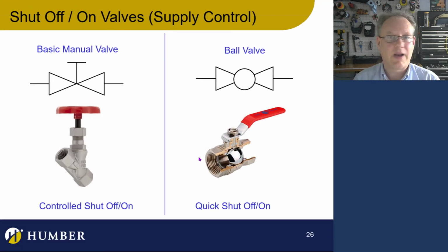So a little bit more ancillary equipment, some symbols, and then I'm going to let you go. Here we have some valves. These are on and off valves. These are the only valves that you will see that only have 2 ports. All other pneumatic valves are going to have an exhaust port. In this situation, we're just turning air on and turning air off. This is a ball valve, which is just pretty much yes or no, on, off.